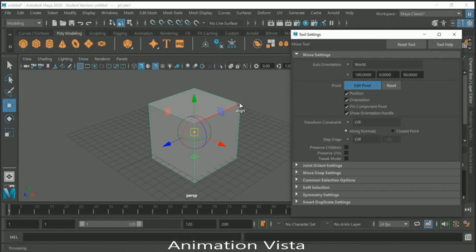if I hover around the edge, corner, or surface of the object, you will notice an Align option around the cursor. What this does is, if we click on the edge, or surface, or corner, it allows us to align the pivot to the position and orientation of the selected edge, corner, or the surface.